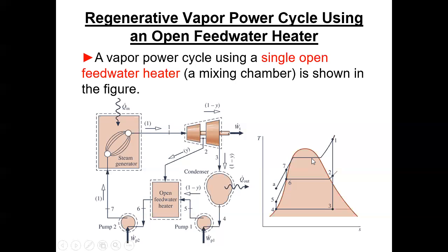No, the Feedwater stays liquid because we are at substantial pressure. Okay. Yeah, exactly. Because in that open heater, we cannot get it to boiling. Yeah, because that open heater is going to operate at that pressure P2, which is still significant. Yeah, that's a good question. Now, we do not boil in the open Feedwater heaters.